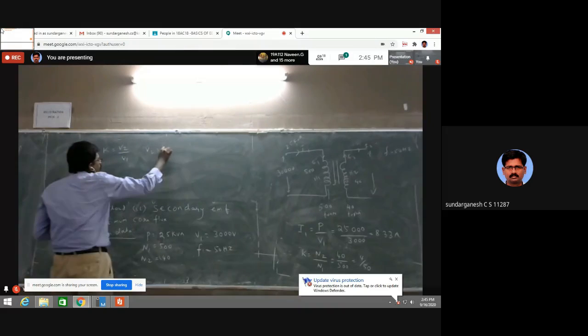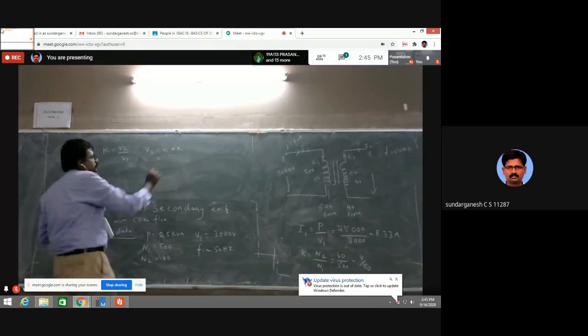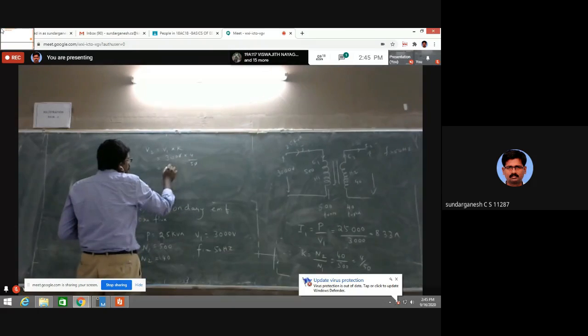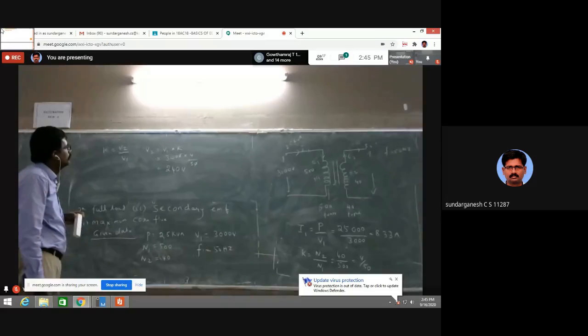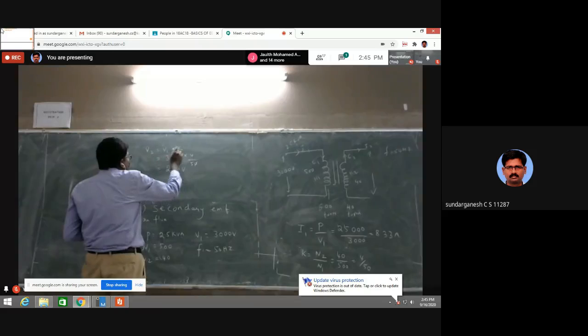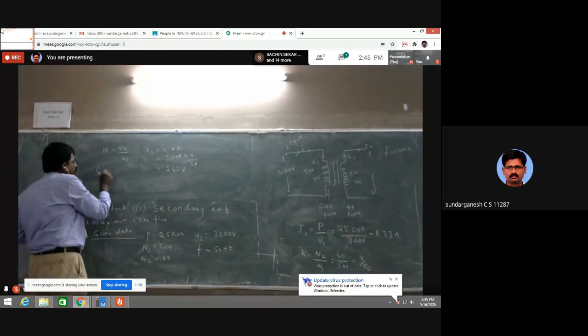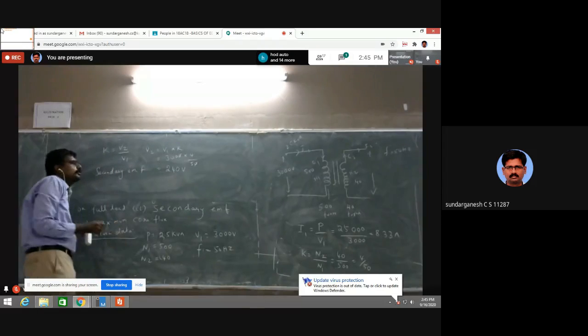V2 equal to V1 into K. V1 is 3000, K is 4 by 50. This is equal to 60 into 4, 240 volts. 3000 divided by 50 is 60, 60 into 4, 240 volts. So I find the secondary EMF. Secondary EMF is equal to 240 volts.